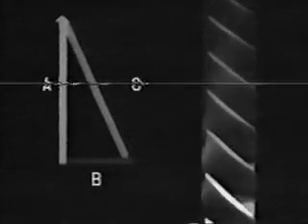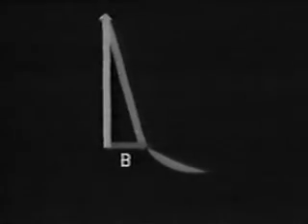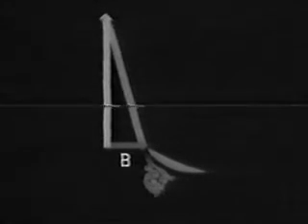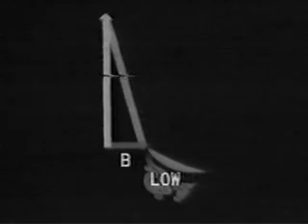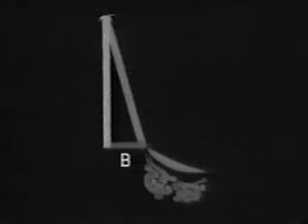If the rear stages continue to choke and the air velocity drops very low, it's easy to see what happens. Though the blades continue to rotate at the same speed, the airflow almost stops. Here, vector B represents very low air velocity. The relative angle of air meeting the foil is so great that turbulence develops. And that important low-pressure area over the foil is destroyed.